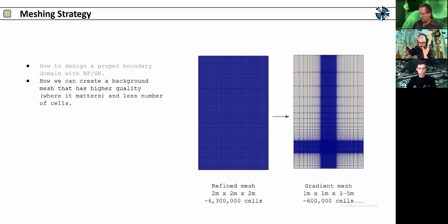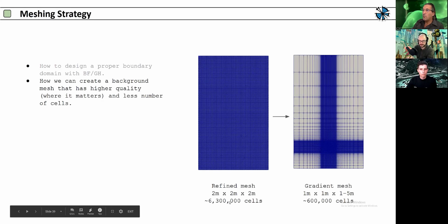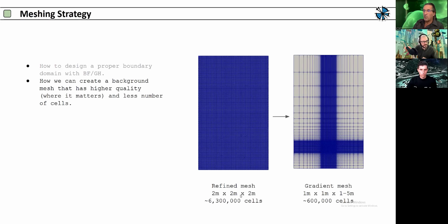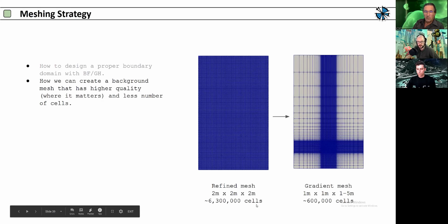Other software, and especially meshing software, like the ones that Professor Spiegelhalter explained, have even better strategies, right? They have something that's called unstructured mesh, which means that you can have different cell sizes at different areas. If you Google ANSYS, you can see a sort of unstructured mesh where the different cell sizes go according to the needs of the mesh, right? Unfortunately, all this software, especially the meshing software, is the most expensive part of the workflow, right? And the only open source meshing software that I know that does quality control is SnappyHex, the one we're using here, and it is a structured mesh.